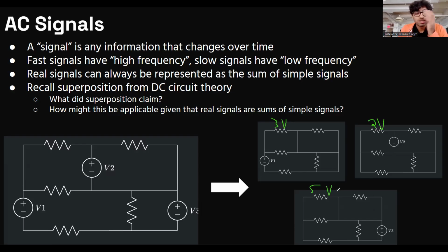That means, and this is a fact, this is the law of superposition in circuits, when I have all three of these batteries in the circuit together, this resistor will drop 10 volts. It's just the sum of the responses to each of the individual sources. This is a really important concept in circuit analysis, especially the linear circuit analysis that we're doing: the fact that sources are superposable. And it's what lets us analyze things with Fourier series.